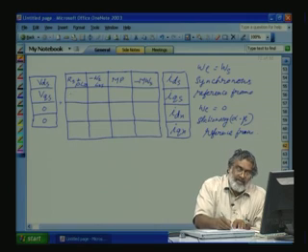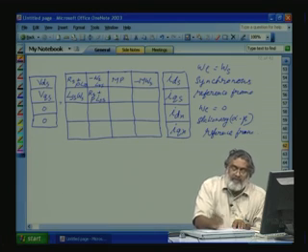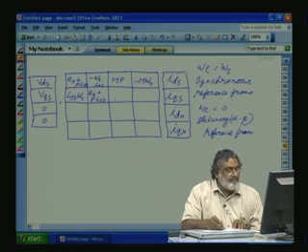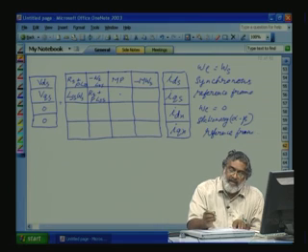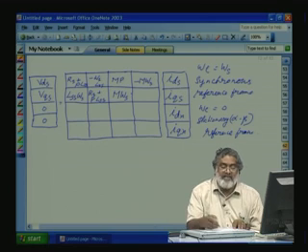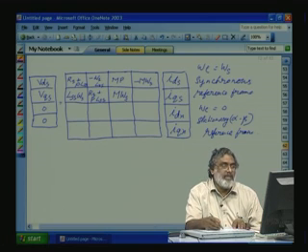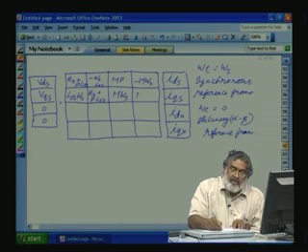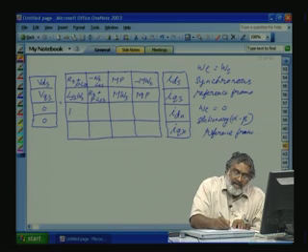Then the stator Q voltages are LSS omega s, then RS plus P LSS, where this P means d by dt of IQS. Okay? Then m into omega s. We are taking everything in the synchronous reference frame, that is the subscript s, synchronous reference omega s. Then m into P, P is the d by dt.